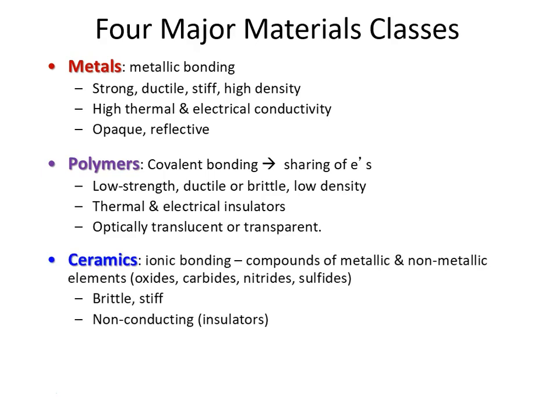Third category is ceramics. These tend to be inorganic, and they are more generally ionic in bonding character, although the oxides and carbides will be more covalent. So they're going to share some of the properties of polymers and metals in terms of the nature of bonding. They tend to be compounds of metallic and non-metallic atoms. So again, oxides like aluminum oxide, or carbides, silicon carbide, iron carbide, which is very important for steel making. Nitrides and sulfides, again, good for fillers and coatings.